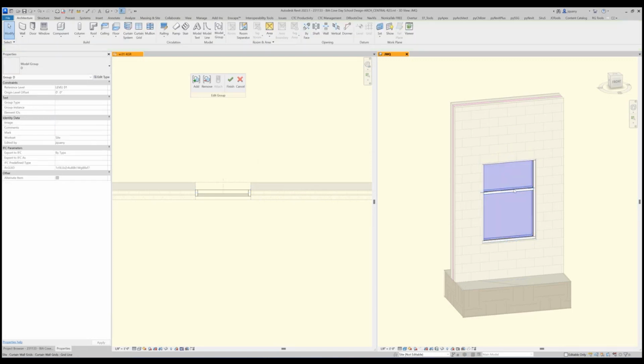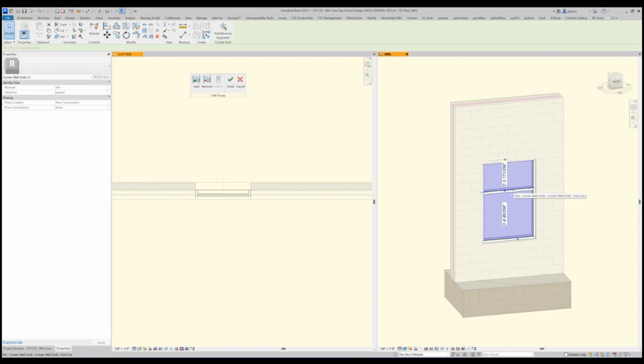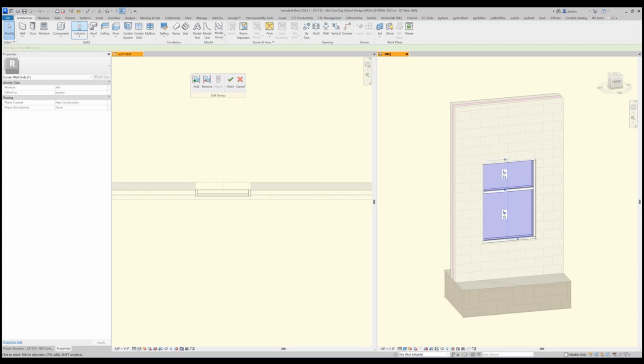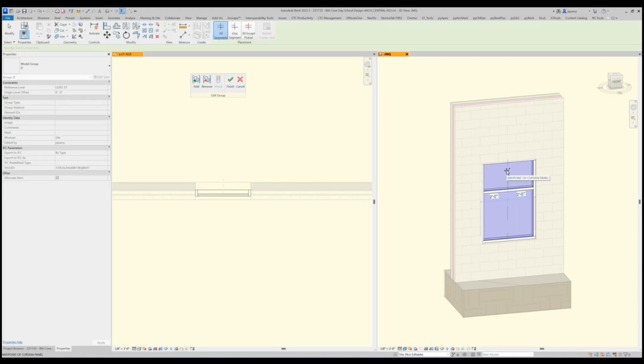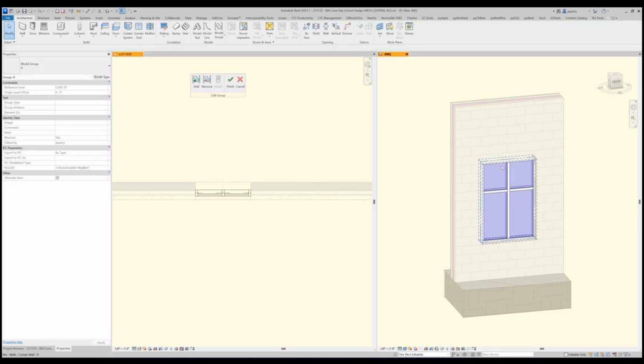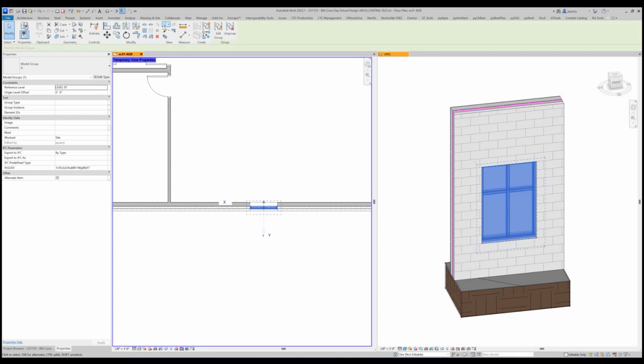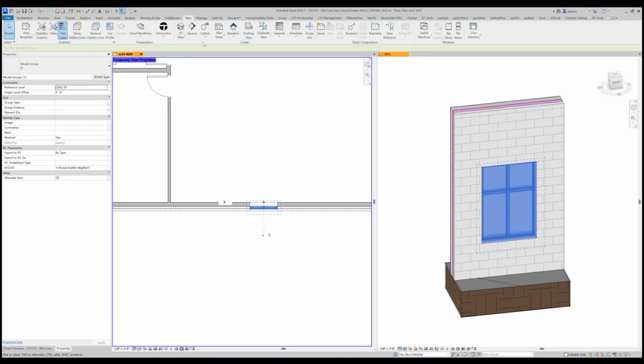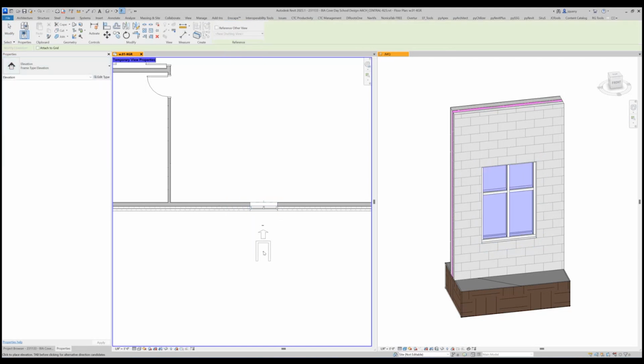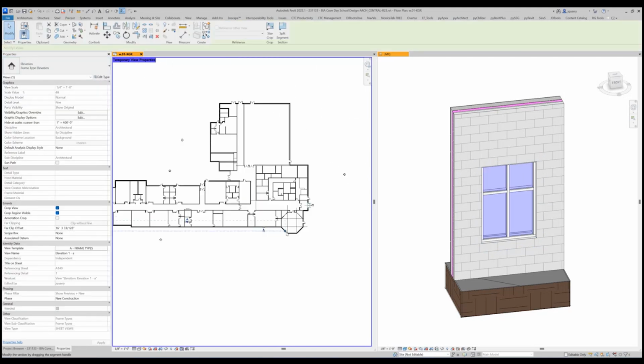And now we can pick this guy and move this to 3'9". And we can place a curtain grid in the middle. I did get it 4 feet, so looks pretty good. It's pretty good to me. Yeah. 6 feet overall, 4 feet wide. So I'll do an elevation, frame type elevation. Take this, shrink it up.